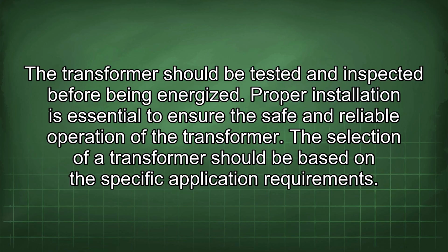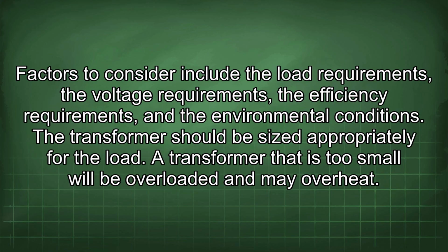The selection of a transformer should be based on the specific application requirements. Factors to consider include the load requirements, the voltage requirements, the efficiency requirements, and the environmental conditions. The transformer should be sized appropriately for the load. A transformer that is too small will be overloaded and may overheat.